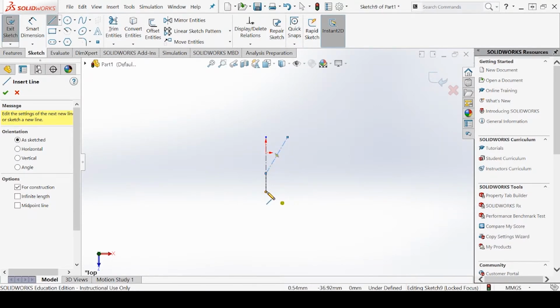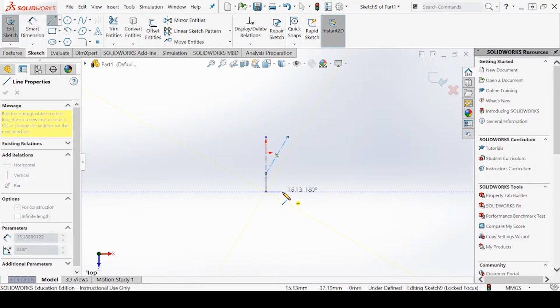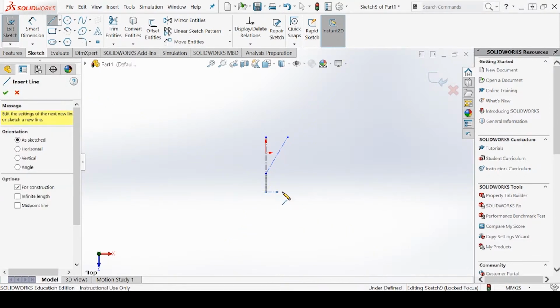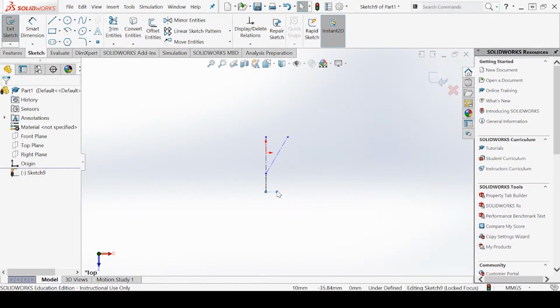Next, I'm going to draw in the radius for our exit aperture. So that's 10 millimeters. And the reason I'm drawing the bottom, or the exit aperture, and not the top aperture is because this point right here and the additional point that'll come when I mirror this over are the two focal points for your parabolic surfaces. So those are going to be important when drawing in those parabolic curves in just a little bit here.